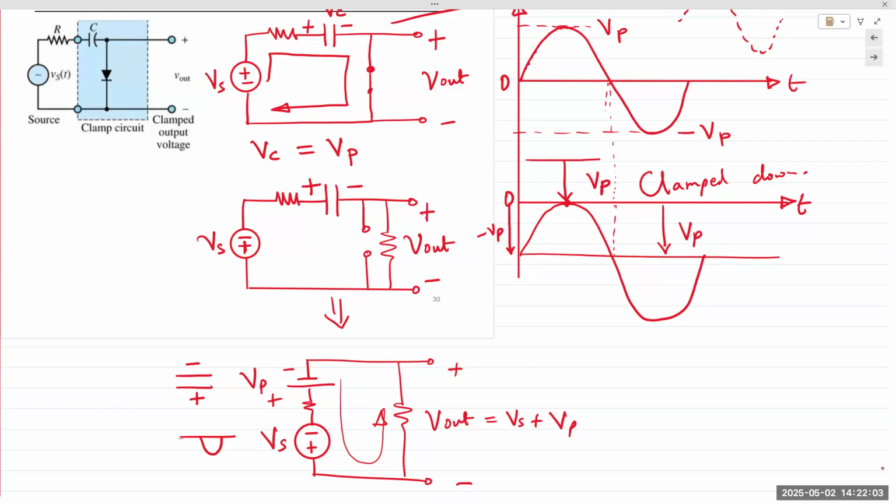Right. So in EE306, which is the EE semiconductor class, we perform the lab experiment where we do clampers. And in there, we use a load resistor, and the load resistor is quite a large value. And obviously, we can also mitigate that. If you want a load resistor that is going to be small, we can always use a capacitor that is very large. But does the clamping make sense?